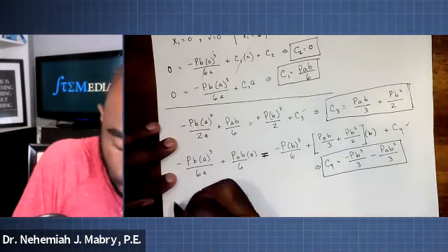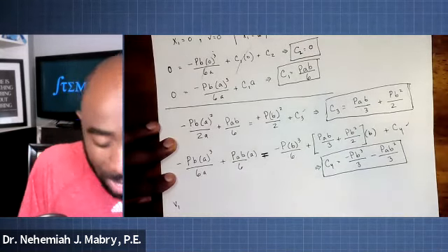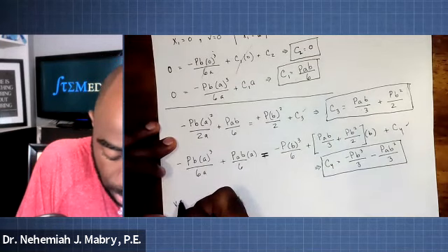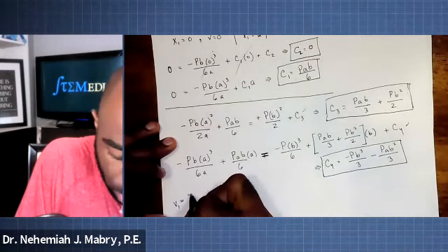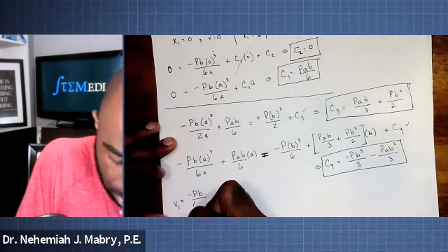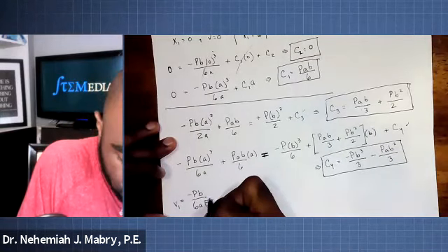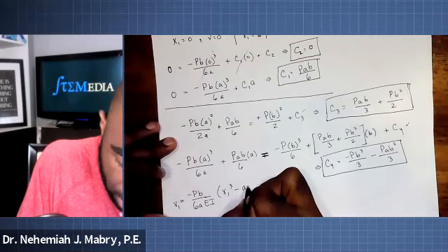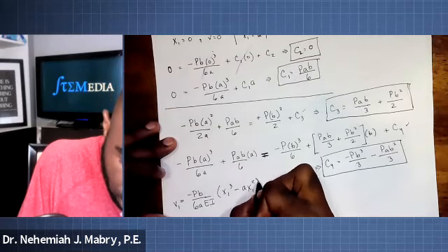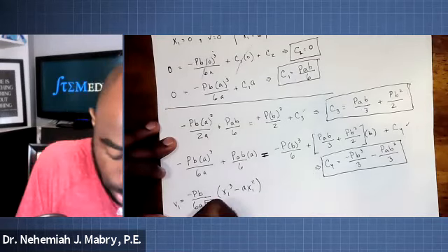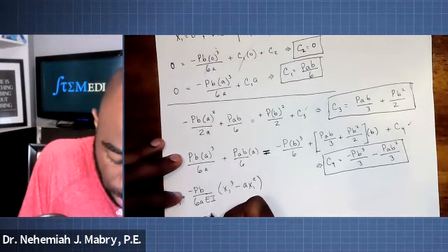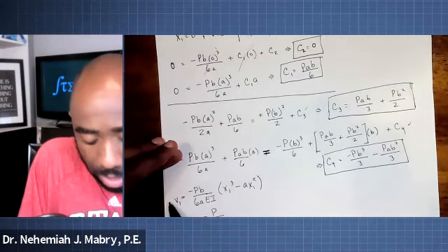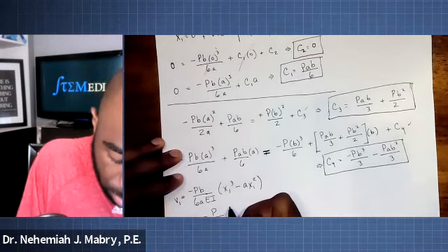And here's what you should get. For the first one, we're also going to divide it by EI, so let's not forget that. Here's what you should get algebraically: P B over 6 A EI times x1 cubed minus A squared x1. And then the other one, when you simplify it, will give you a negative P over 6 EI. We're moving the EIs from the other side in order to answer these problems.